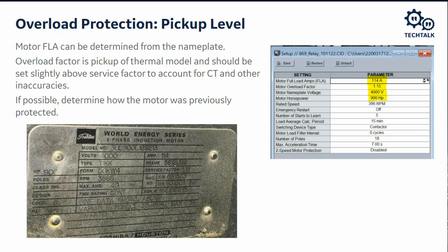So it's a combination of an ability to overload, an inherent conservative nature built into the overload curves, and 100 years of history of these overload curves properly protecting the motor, that the overload factor comes in there. And so that gets us our pickups and motor overload factor.